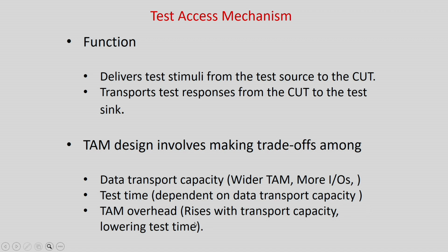So if you put a lot of TAM resources, then a lot of test patterns can be applied in parallel and faster, and that will actually lower the test time. But the TAM DFT cost will be rising.